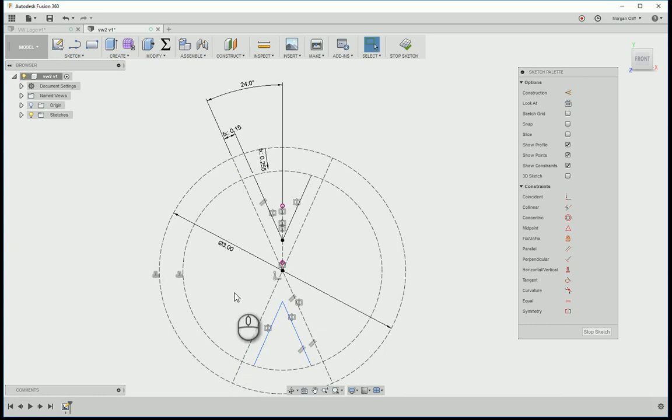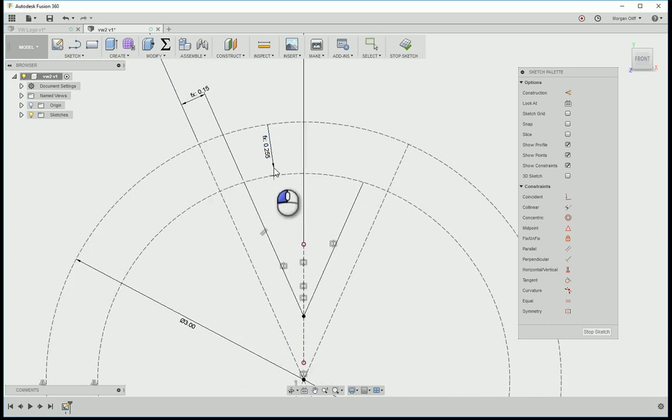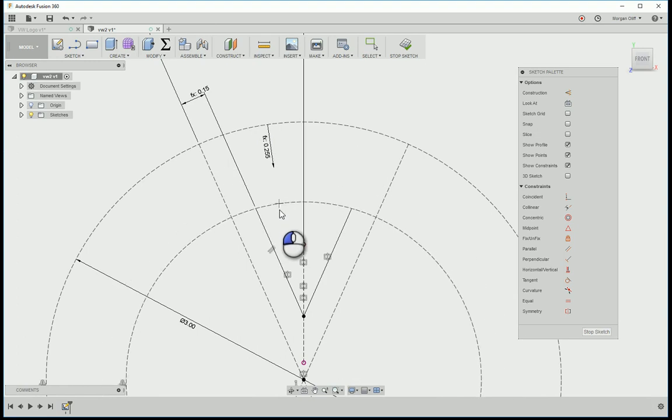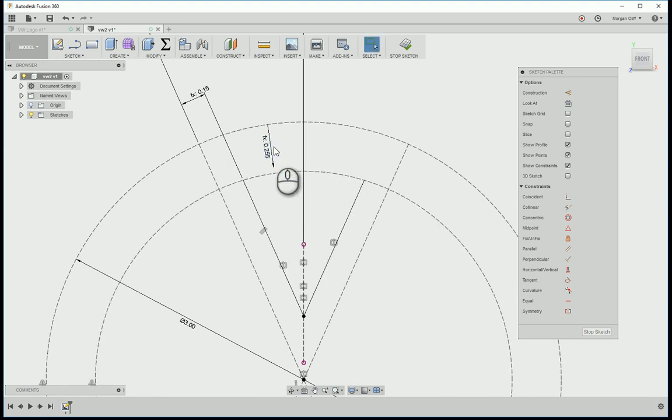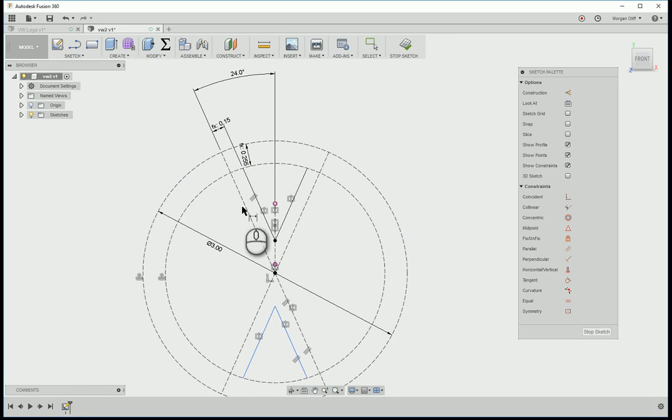Not at all what we wanted. What happened? So we had a dimension here, but it didn't even stay attached. No idea. I've had that happen before, but I'm not sure why it happened now. So let's try again. So we can get this dimension again, and we'll click this 3-inch base dimension, times 0.085, enter.